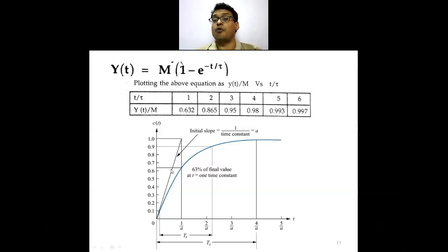If the temperature gradient had remained constant at 3.6 degrees Fahrenheit throughout, then it would have followed a straight path. But the gradient cannot remain constant as at time 0. It has to decrease, and that is why it follows a curved path.